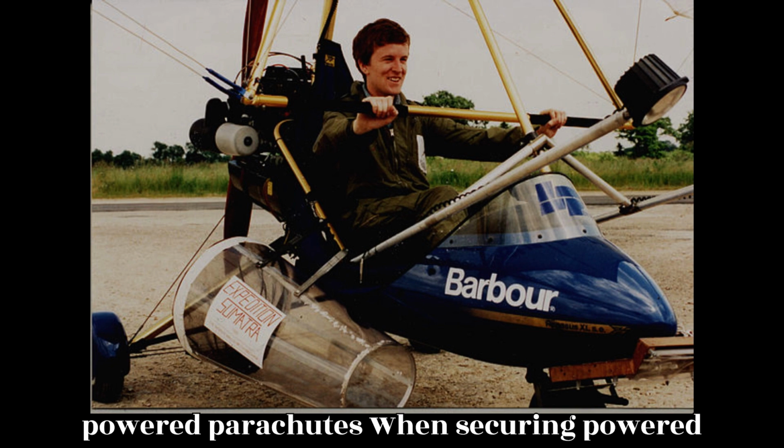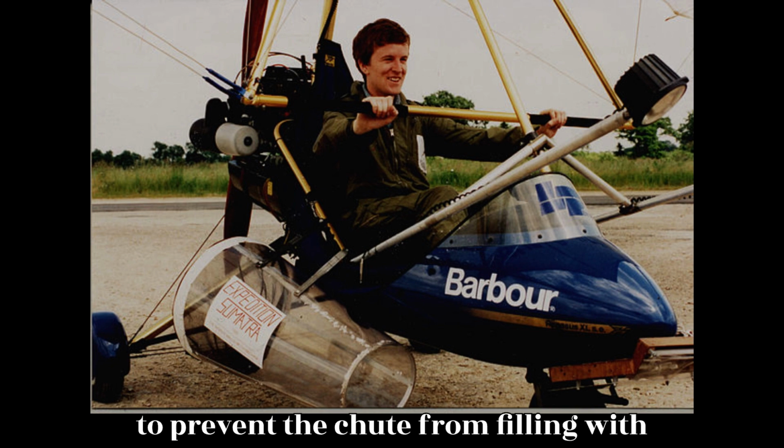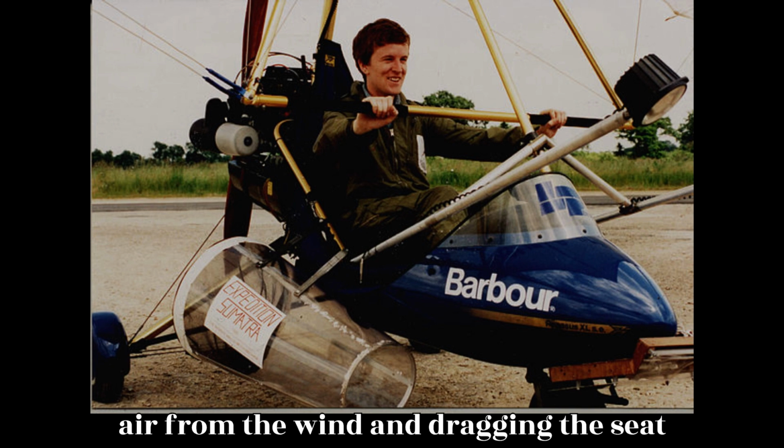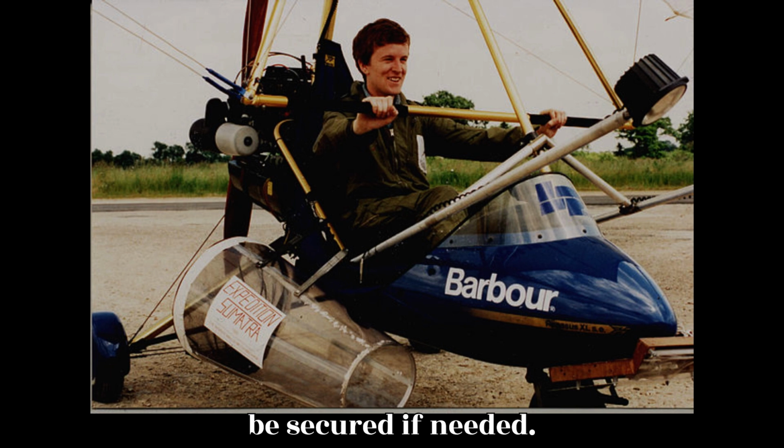Procedures for securing powered parachutes. When securing powered parachutes, pack the parachute in a bag to prevent the chute from filling with air from the wind and dragging the seat and engine. The engine and seat can also be secured if needed.